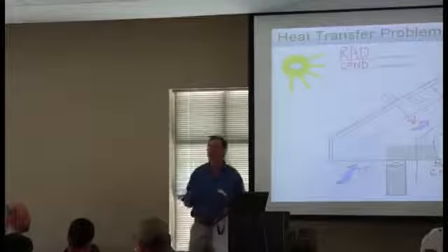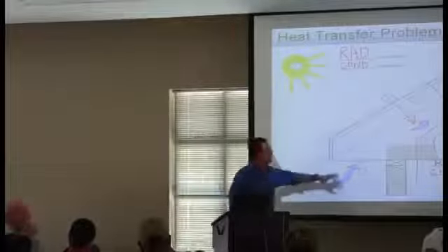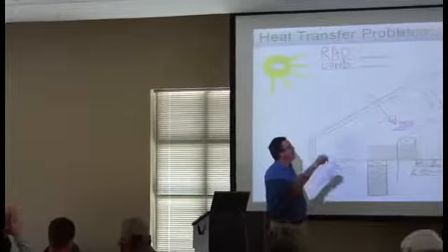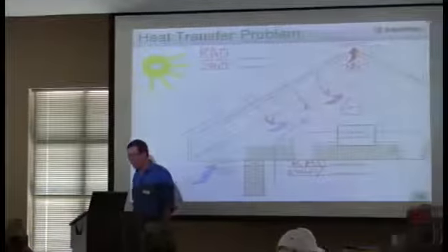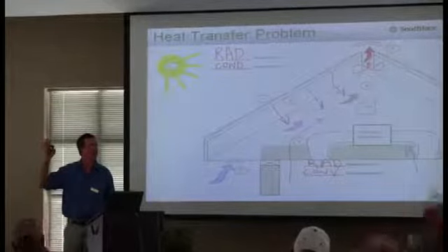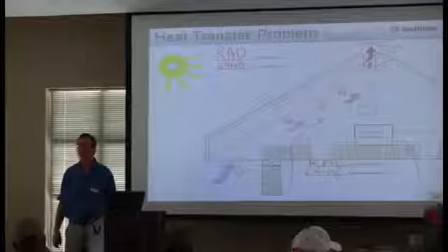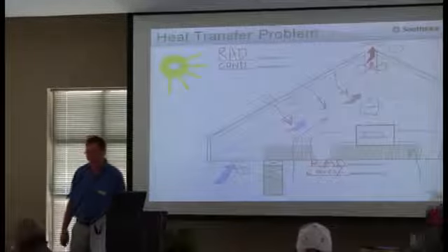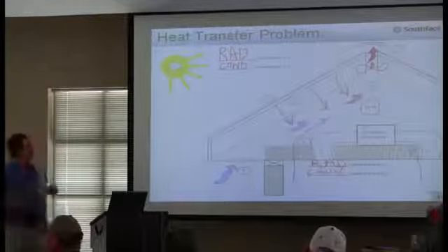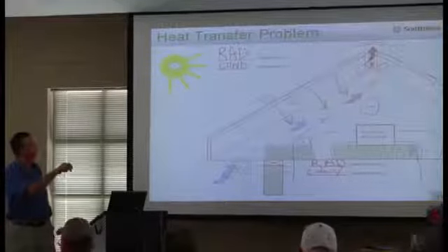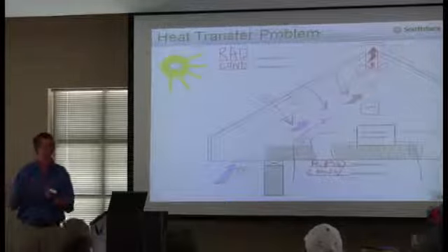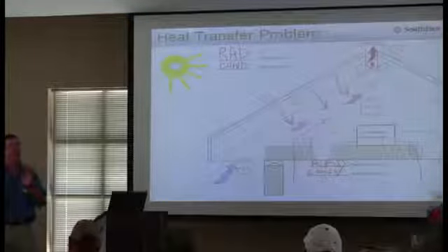Okay? The only other question we sometimes get is, what if I changed my building thermal envelope and I foamed the roof line? And we've actually had a lot of houses that have done that. Has anybody been in a house or done this on a project before? Did it work? It actually works extremely well. And the reason it works so well is a couple of things. One is because it's very, very airtight, because the foam itself is both an air barrier and an insulation. It's also very expensive, so I'm not saying there isn't a cost associated with it.